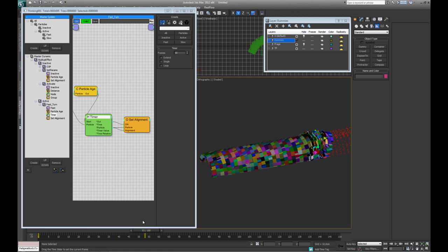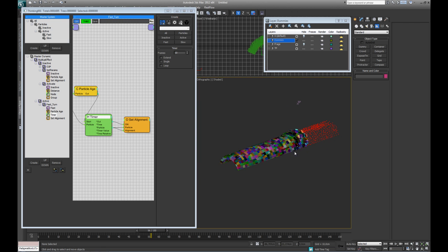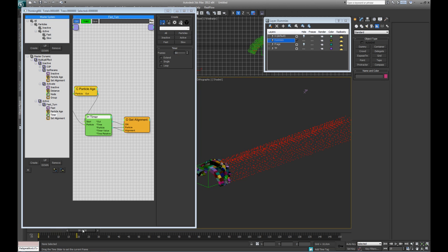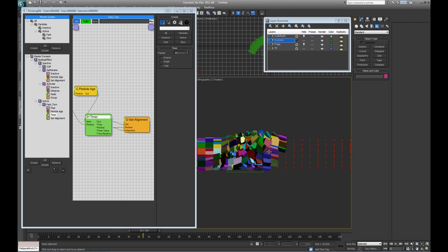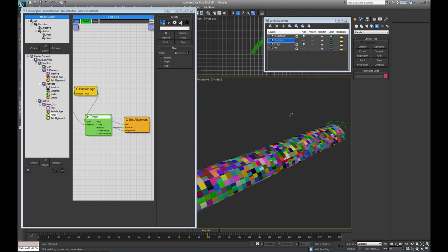However, there is a problem, and it doesn't make a full turn. For some reason, I'm not really sure why, because I'm not that experienced in Thinking Particles yet, you need to take the amount of frames you want it to do and add 1. So if you use it over 11 frames, we're going to have a perfect build-up effect. You can see now we have this awesome clumpiness to it, and then everything rotates back into place, which is what we want. So this is actually the effect done for now.